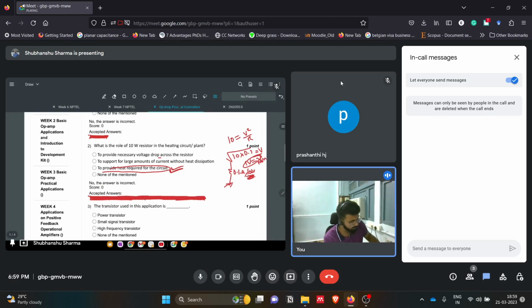So the voltage across this can be maximum up to 1 volt. If we have a lower power rating, let's say 4 watt for simplicity of calculation, then this voltage will be reduced. It will be 4 into 0.1, that is 0.4, so the voltage will be the square root of 0.4, about 0.63, which is less than this. So in the earlier case it was 1 volt max, up to 1 volt we can get here.